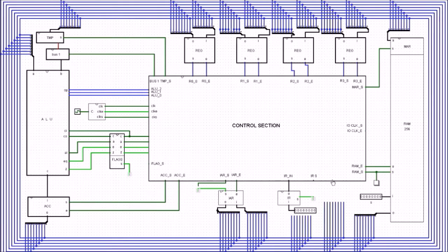So you can see here that we have the CPU that we've seen over the last few videos. It's got all the same components, but in this instance we have this extra component here, and this is the very last register that we're going to add in, and this is the flag register. Whenever we do this JUMPIF, we're going to make a comparison, so we're going to see whether any of these are set. So we're interested in whether the carry out is set, the A larger, the equal is set, or the 0 is set.